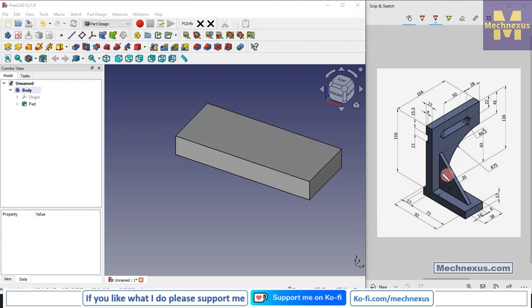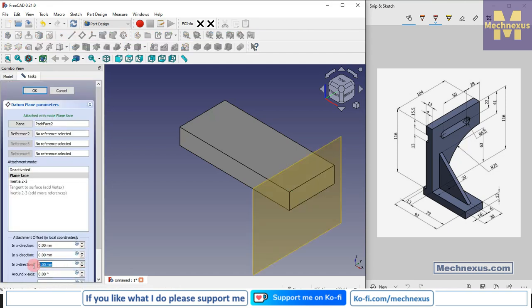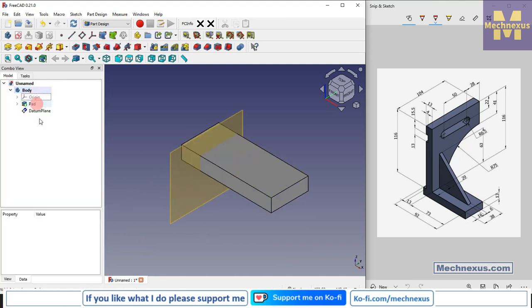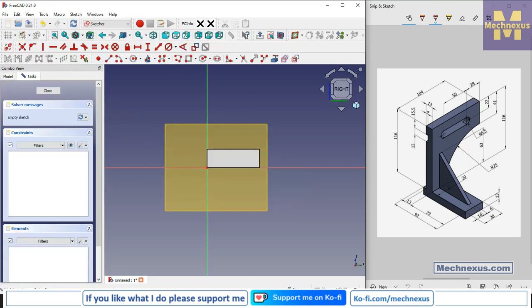And now we will create a datum plane from this face. Here the distance is 73. So press 0 for isometric, select this face, and click here on datum plane. In the Z direction provide the value 73, and change the sign from plus to minus so that the direction of the plane gets reversed. Click on OK. Now click on rebuild.